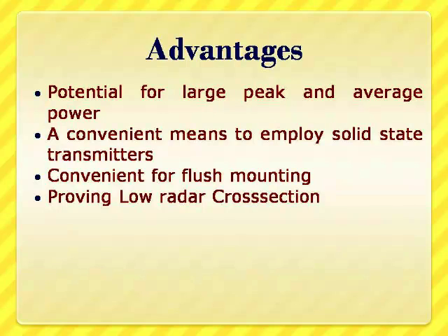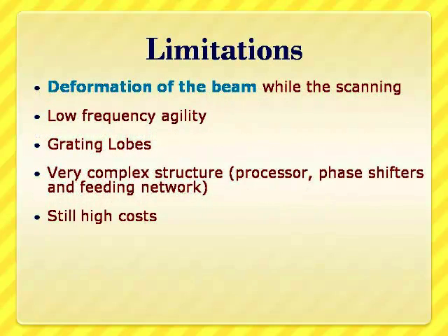If we can go for a microstrip antenna array, we know very well that it can be flush mounted onto the surface of this system. Like it can be an aircraft or a missile or any other device like that which can have a curved shape. By this, we can see that the antenna array will have a low radar cross section. That means this radar system antenna may not be easily identifiable by another radar system. That is how we say that the radar cross section of this is much less.